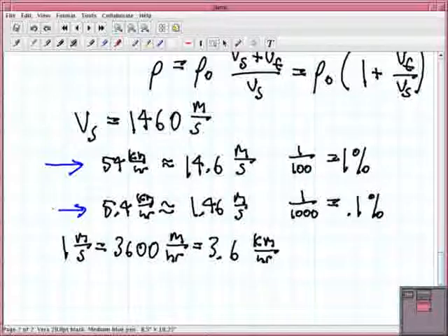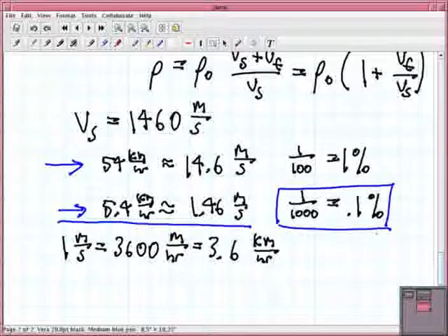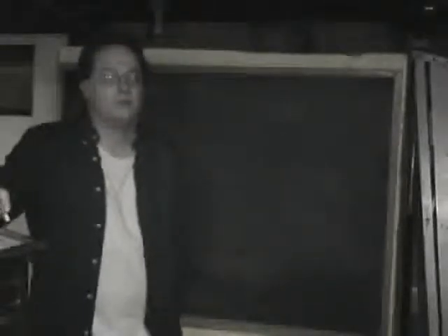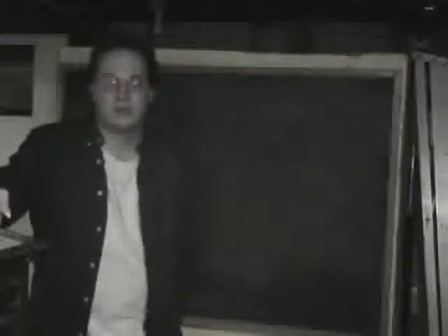So we see certainly with this one, with a very reasonable flow rate of water, we can expect to achieve a 1/1000th increase in the density. And as we'll see in a minute, the increase in density of 1/1000th is going to result in a much more significant increase. The isothermal compressibility is a fluid property. It's approximately linear, and actually for most liquids it's a very good approximation for it to be linear.